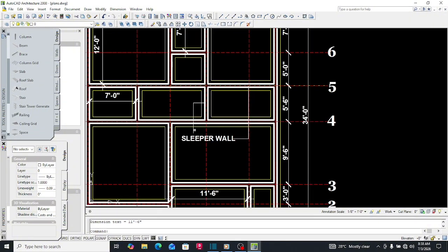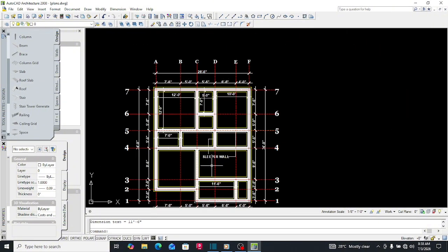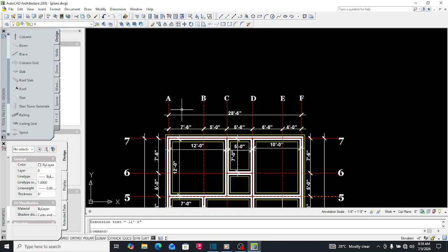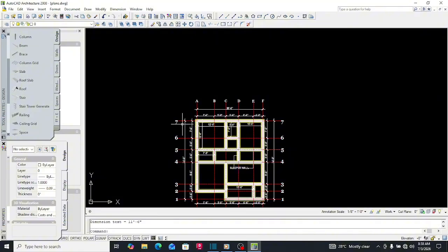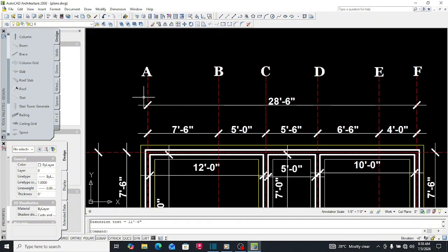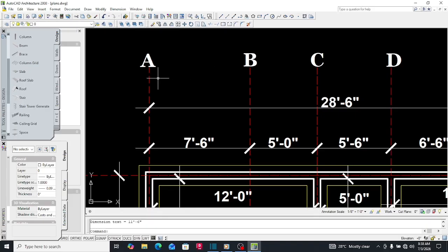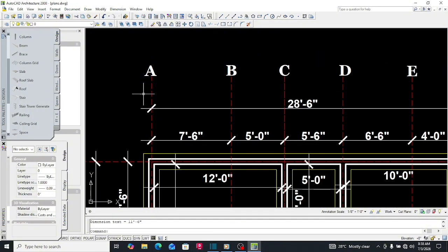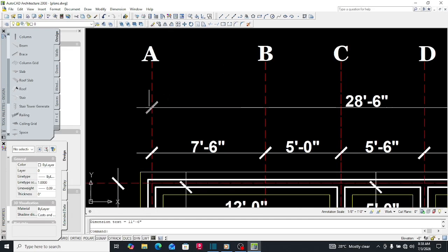So now we know why we introduce a slipper wall in the foundation plan. So now let me explain the grid lines. Now the grid lines is what they are going to use. So when you are doing the profile, you fix the pegs and the boards and everything on the land. Now the nails, you are going to use the nails to represent. So this line represents a nail. This line represents a nail.